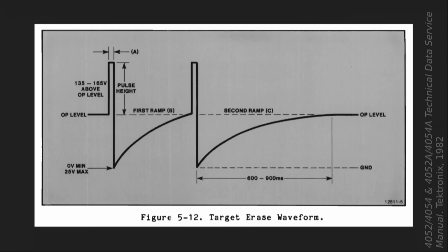So I ran out of time to make animations to explain what's going on here. So as a substitute, I'm going to try to make this voltage over time graph come to life for you with sound effects. Please prepare yourselves. So it all begins on the left-hand side when the target voltage is raised to 150 volts. Electrons drain from the faceplate. Flood gun electrons go zip and impact vigorously into the draining, newly positive screen, flashing it green like we've seen.